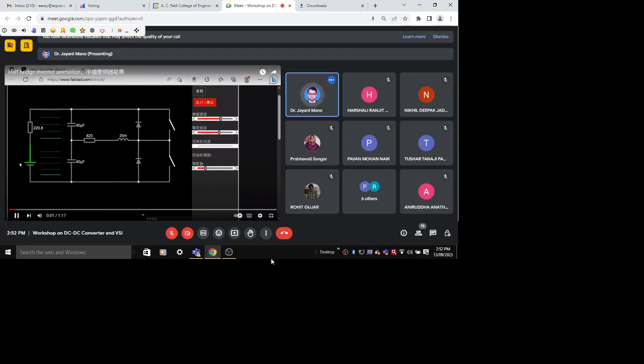So once again, you can see this animation. This is the DC bus split in capacitors. So this is the initial biasing. Initially, these capacitors are charged. Now this switch is on. Current is flowing in the upper part, which is off. Once again the upper switch is on, just to show how it works. Then the lower switch is on. See, the current is in reverse. So that is how the DC is converted into AC. So these switches are turned on and off.